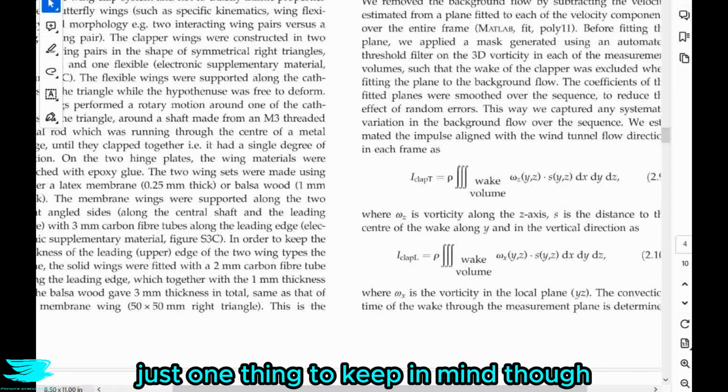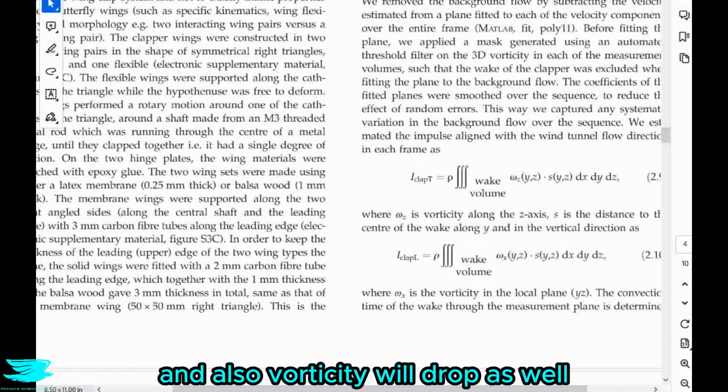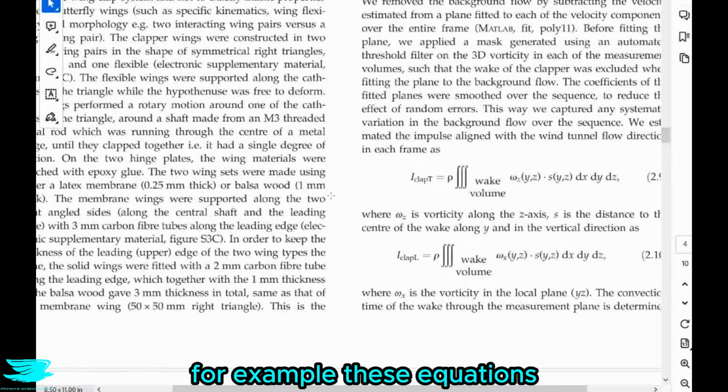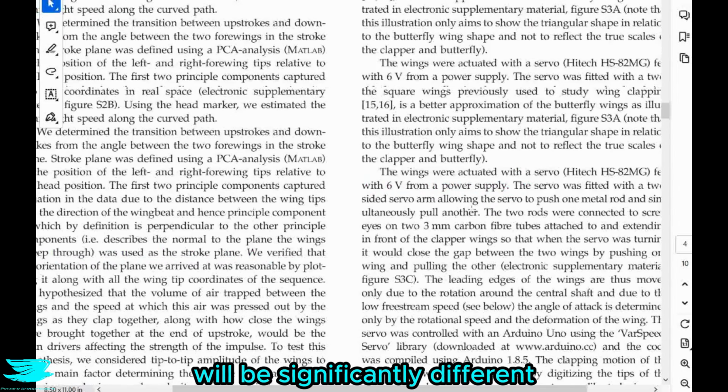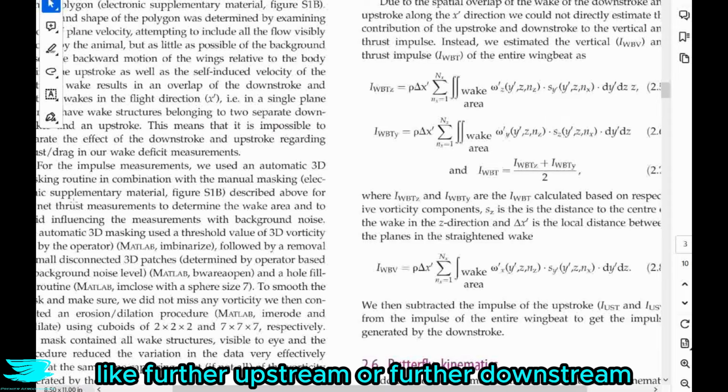Just one thing to keep in mind though is that because of viscosity, as you go downstream, the effects of the butterfly that it has on the air will drop as the additional momentum imparted onto the air will get converted into heat, and also vorticity will drop as well. So that is something that has to be kept in mind, because if you measure the wake 1 meter downstream, for example, then it is broken down a lot more than if it was just being produced, and hence the forces that you will calculate from, for example, these equations will be significantly different than if you had the wake plane higher, like further upstream or further downstream.